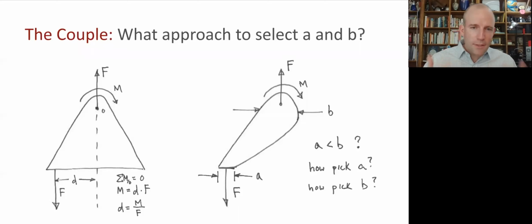All right, so when I ask you what should the numerical value be for some parameters, the first thing you should think of is inverse analysis. So in this case, we're going to think about what is the stress model down here, what's the stress model up here, and then plug in what we want the stress to be, the strength divided by the factor of safety, and then solve for this parameter A or B to figure out exactly what it should be.